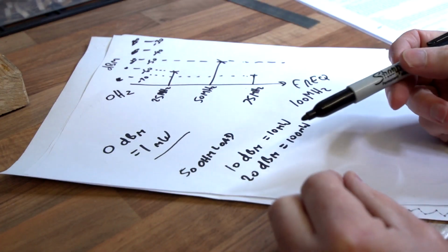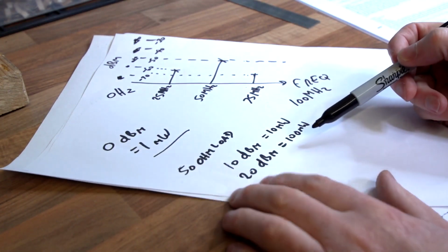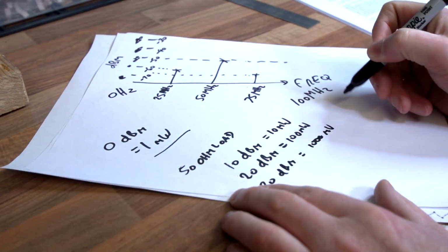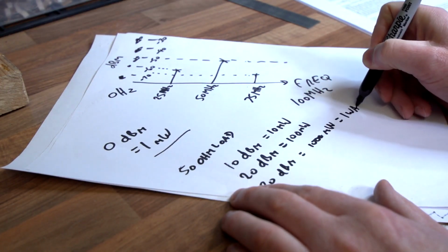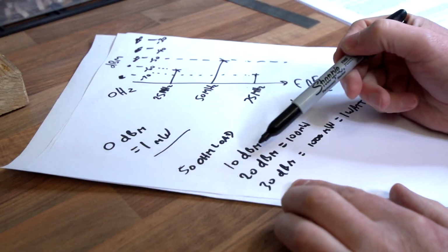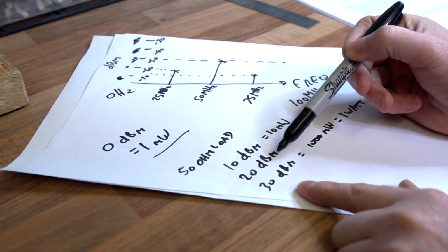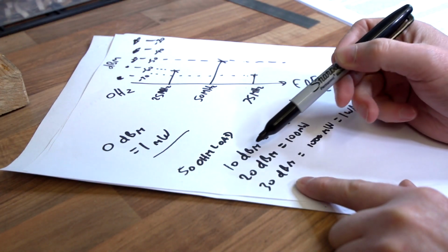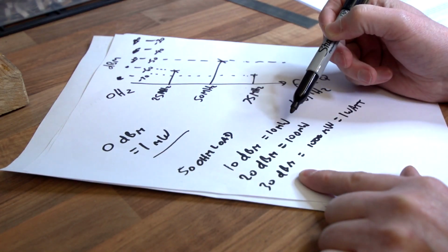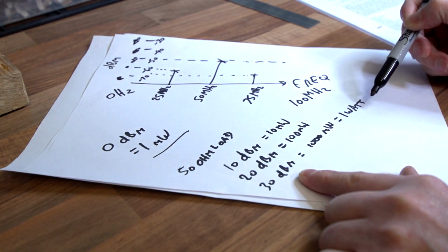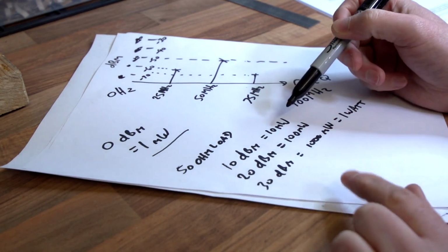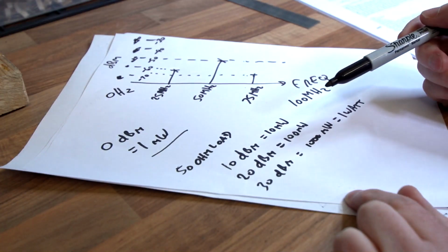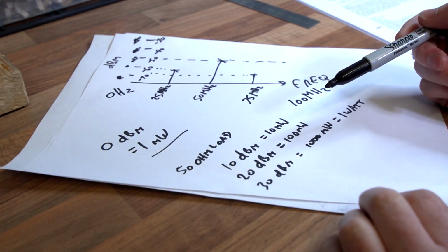And that's the logarithmic nature of dBm. A 30 dBm, what would that be? That would be 100 times 10, which is 1,000 milliwatts, which is 1 watt. So within 2 divisions, if you think about it, that would be a square on the screen, or graduations here. From 10 to 30, you've gone 10, 20, 30. So that's within 2 divisions. You've displayed a signal from 10 milliwatts, which is really small, right up to 1 watt, which is 100 times bigger. So we're really showing a big range of signal for a small amount of actual display, if you want to call it real estate, the part of the display that you can visibly see in one go.